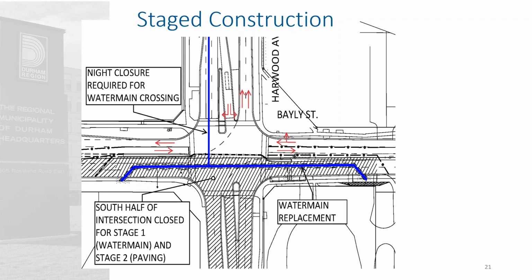that concrete pavement. There was a new water main replacement included in this contract as well. So we did the water main first, and then did that concrete pavement on the south side, and then we flipped this. So we pushed traffic to the south and worked on the north half of the intersection. So it was closed half at a time. We discussed doing this in quadrants to avoid the partial closure, but especially with these islands, it was just too finicky and there wasn't enough room for the contractor to work, so we ended up designing it this way.